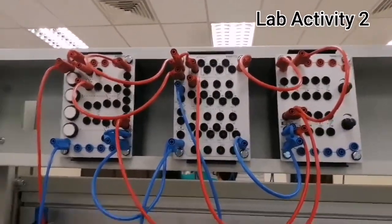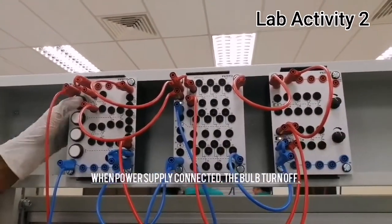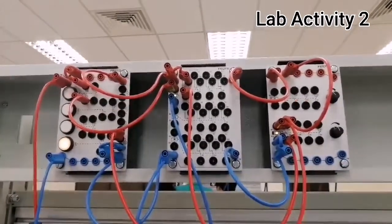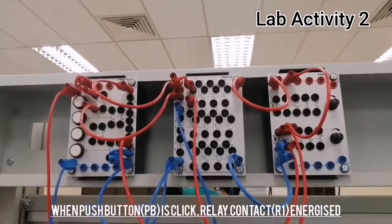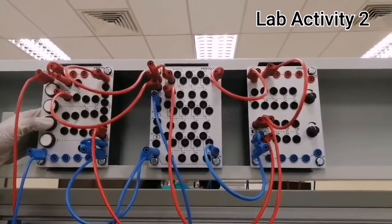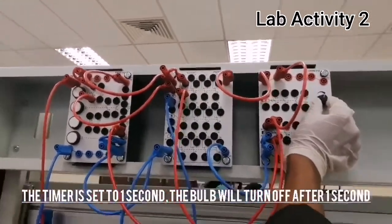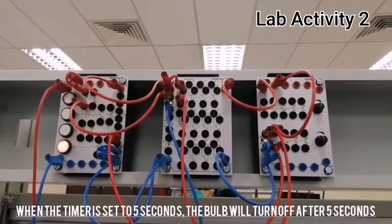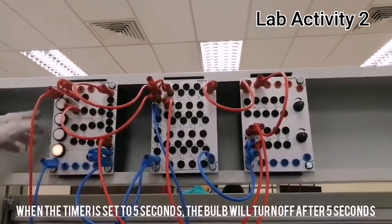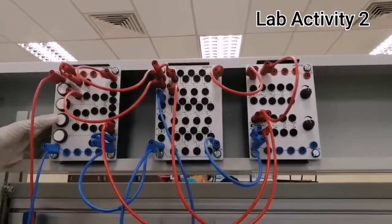For task 2B, when the power supply is connected, the bulb will turn off. When the push button PB is clicked, relay contact R1 energized. The timer is set to 1 second. The bulb will turn off after 1 second, and when the timer is set to 5 seconds, the bulb will turn off after 5 seconds.